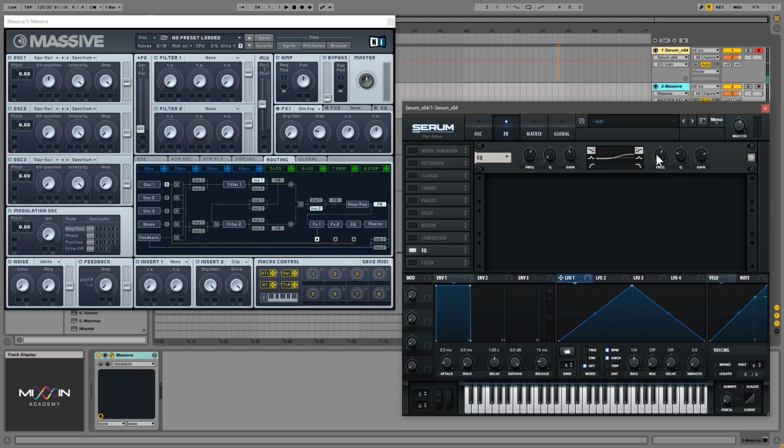And we can, of course, make both of these into peak filters, just like that, where we can control the bandwidth of the filter, the frequency, and the gain. So they can actually boost or attenuate certain frequencies, the band of frequencies that we chose.